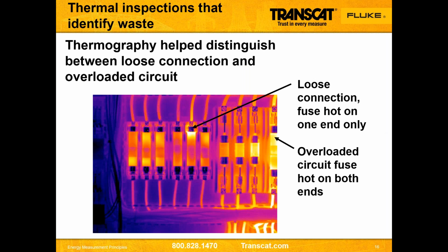This is kind of what this would look like. If I had a thermal imager in my hand and had the cabinet door open, the connection in the center here, where it says loose connection, could be loose, dirty, or corroded, right there at the top of that fuse clip. And I can see that with the thermal imager. How we would actually measure that is take a Fluke voltmeter and measure from the top of the circuit to the bottom and actually confirm, based on the voltage drop, that it's a highly resistive connection, i.e. it needs to be fixed on my next maintenance shutdown.